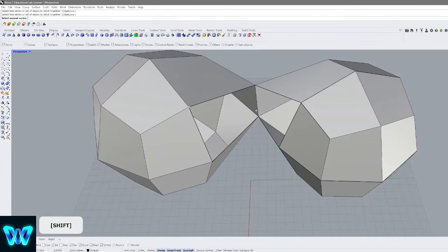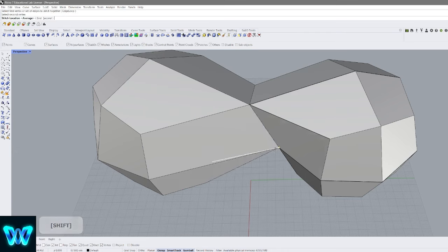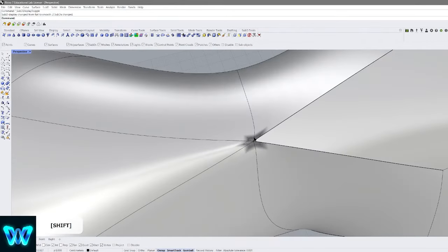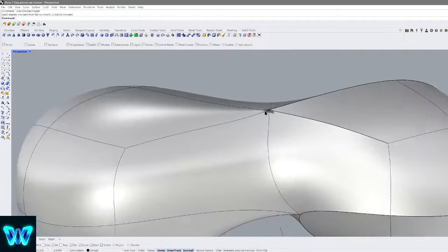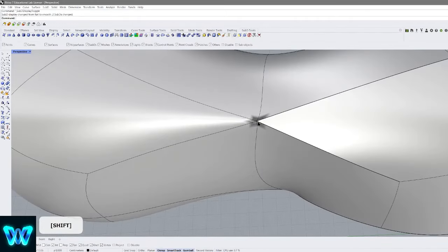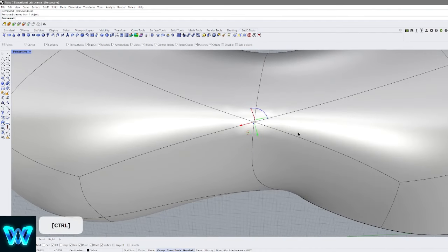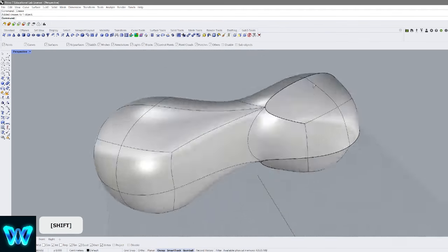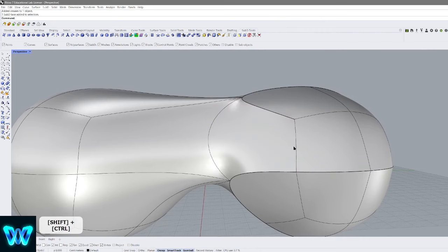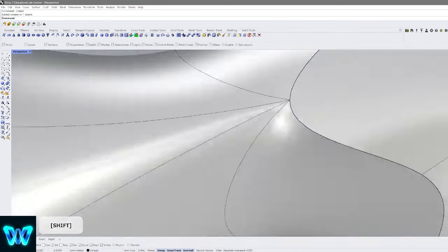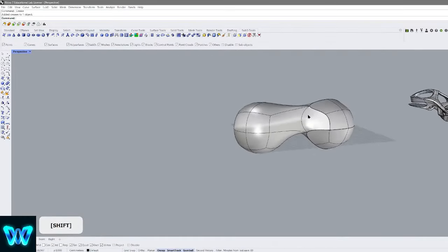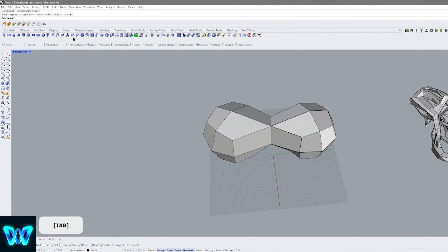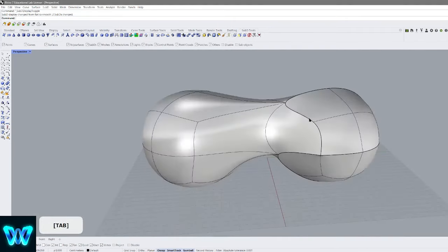and I keep stitching them, you're gonna see that the creasing in this edge loop works pretty weird because it's just being stitched. So what you have to do is uncrease this, and then crease it again with those loops that you were creasing, and now you will have that curvature that you were probably expecting. So it's one thing to really make sure you do when you stitch. That's why it's so important to switch between polygonal and non-polygonal mode, which is called flat to smooth. So that's probably a better way to call it, flat to smooth.